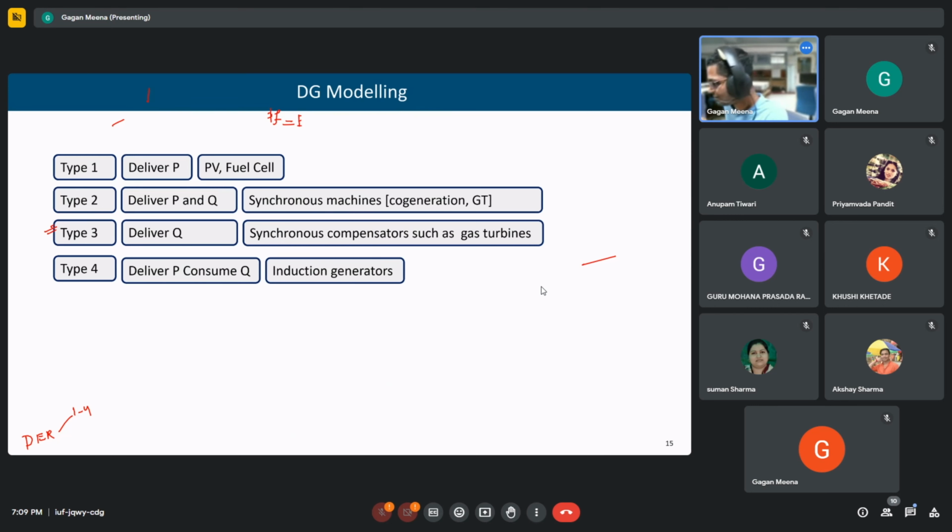The principle which governs the induction machine requires reactive power, so that the electromagnetic or electromechanical conversion can happen. So where does that reactive power go? If it is an induction motor, it will consume active power, and whatever mechanical motion happens, it does some work because of that active power. But where does the reactive power go? It goes into establishing the magnetic flux, which generates that work.